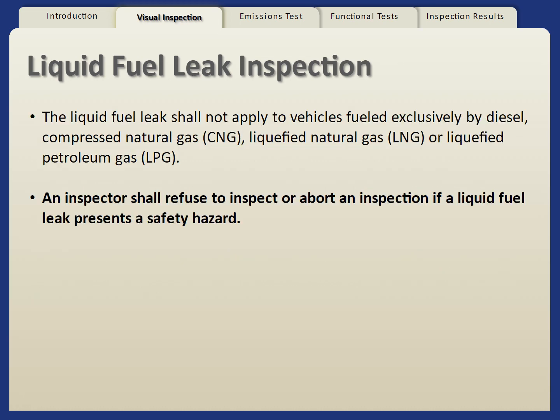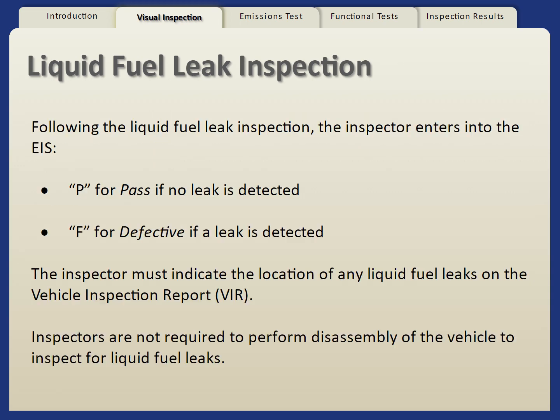The liquid fuel leak inspection shall not apply to vehicles fueled exclusively by diesel, compressed natural gas, liquefied natural gas, or liquefied petroleum gas. Nothing in the liquid fuel leak inspection shall prohibit an inspector from refusing to inspect a vehicle or from aborting an inspection if a liquid fuel leak presents a safety hazard. The liquid fuel leak procedure is a visual inspection only.